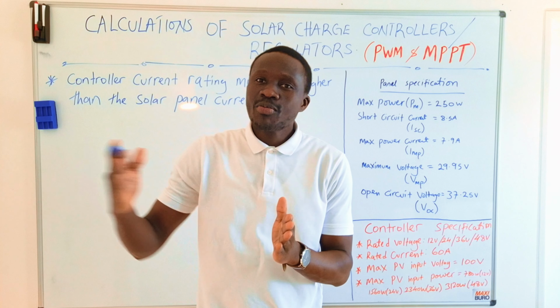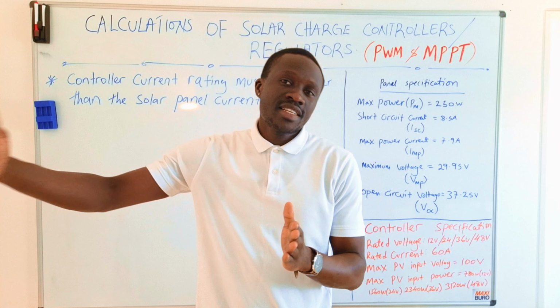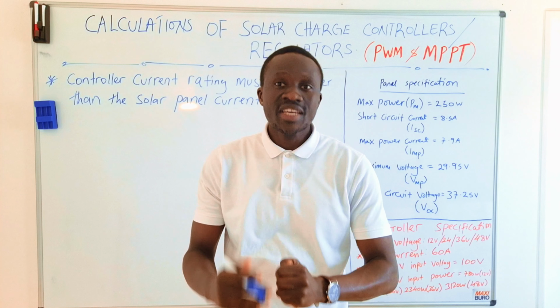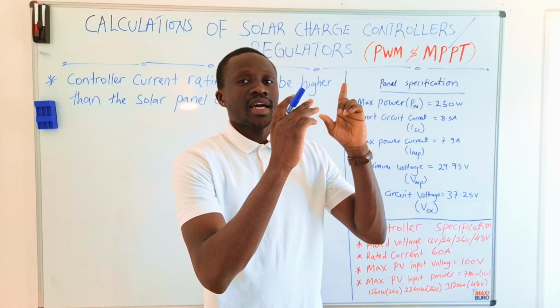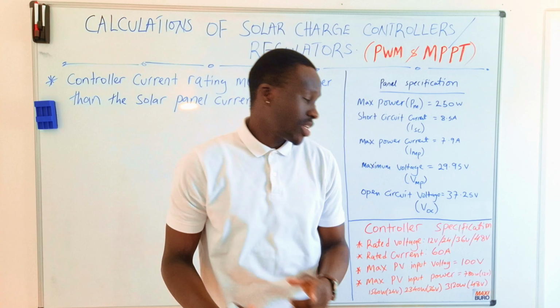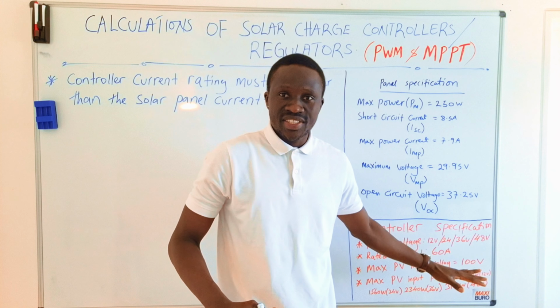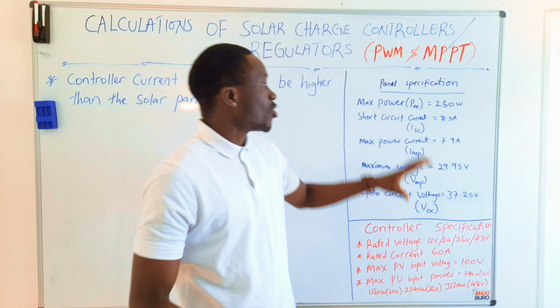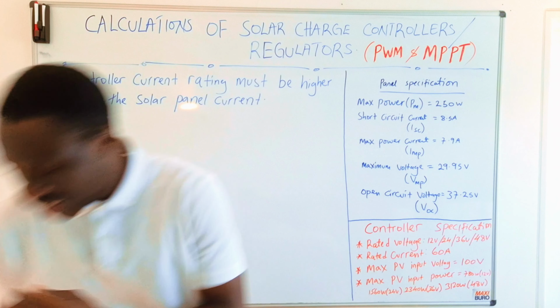Now, more than 3000, you can use a 48 volt battery. You connect your batteries to make 48 volts, when your panel is producing more than 3000 watts. That is the information you can see on the sticker behind the regulator or behind a solar panel.